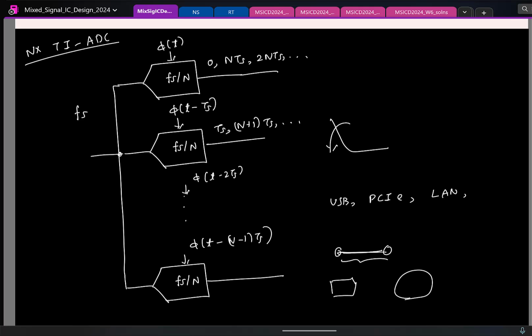And these high-speed ADCs will sit at the receiver end, and loosely speaking, its job is to just see if the received bit is 1 or 0. That is the layman's explanation. You think that it's all digital, but at the peripheral you have a whole bunch of analog mixing, and these are called wireline communication. It's a separate topic by itself, and they usually call it a SERDES, meaning serializer and deserializer. Again, it's a different topic. But you get the idea, right?